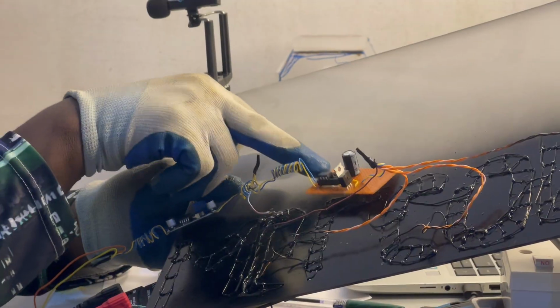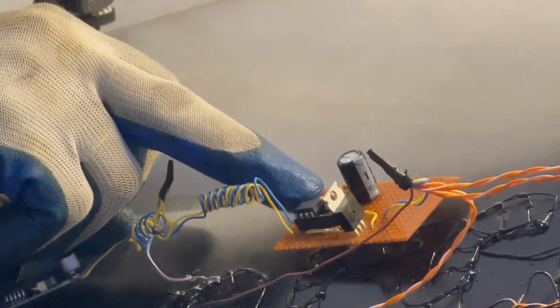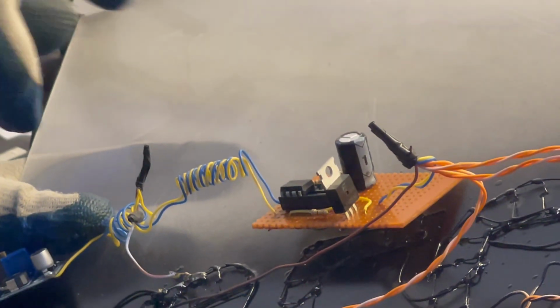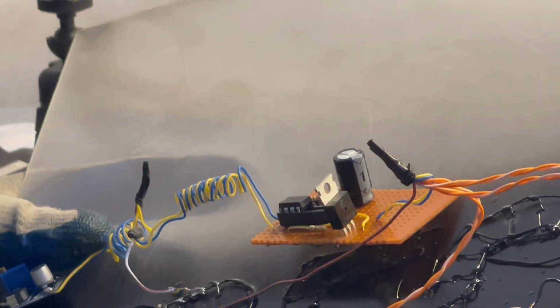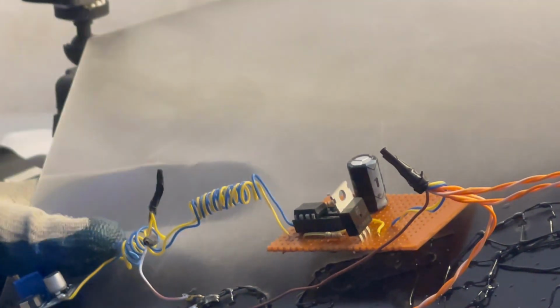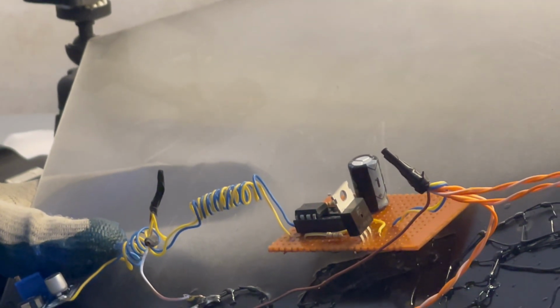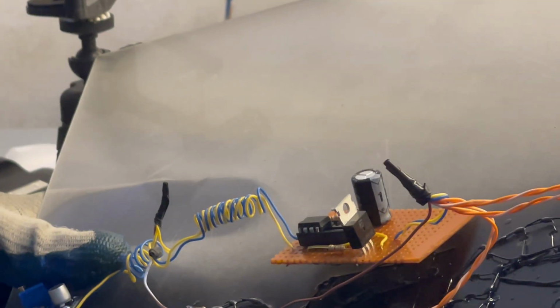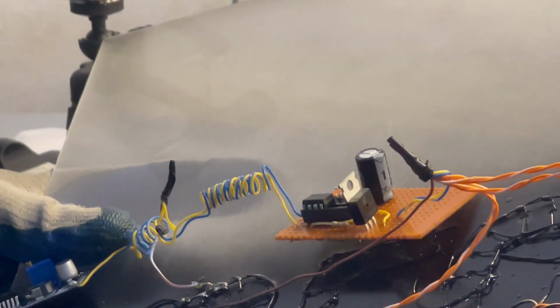Now for the R1 value, there is a resistor connecting pin 7 and 8. You have just 100 ohms. Then from 7 to 6, you just have 1000 ohms. Remember that 2 and 6 are going together, and 4 and 8 are also connected together. Your output comes from pin 3, in the circuit I'll be sharing in the description section. We tell everything, just look at it and design it.